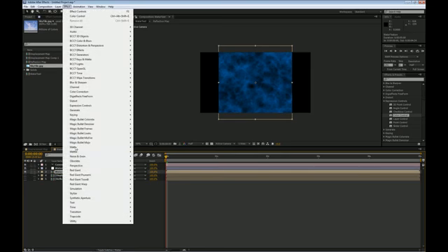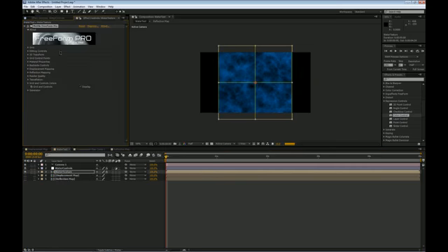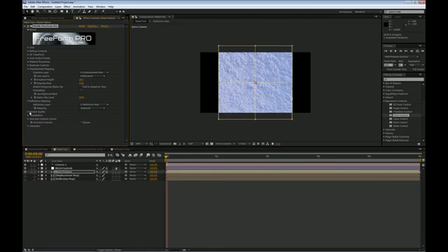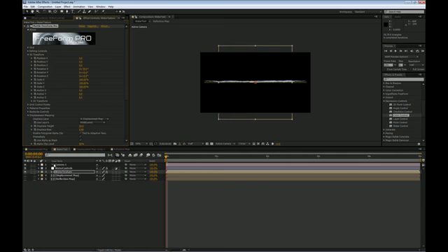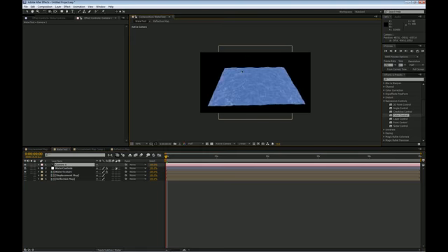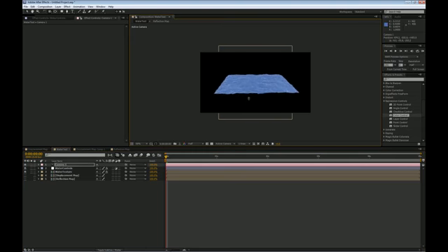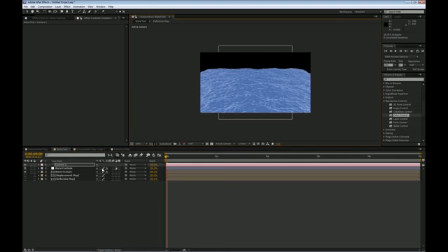On the water texture, I will apply Metal Freeform Pro. Use for displacement mapping my displacement map, reflection mapping, my reflection map. The render quality, I'll set this to low, and for the anti-aliasing, I made sure that the adaptive tessellation is on. And I will use the 3D transform controls here to rotate this on the x-axis minus 90 degrees. Now I can go ahead and position my camera to show you what's going on. There we go. This is our water.